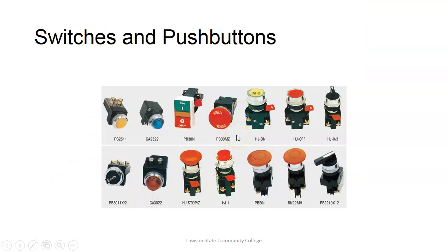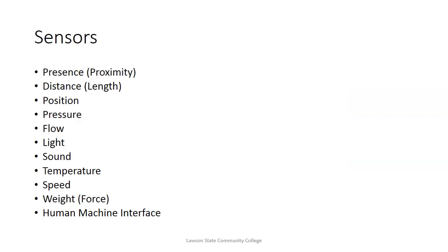So these are selector switches or push buttons. These don't have a polarity, so there's no such thing as sinking or sourcing push buttons. So this doesn't make any difference. When you get into your solid state sensors, this is going to actually come into play. So, sensors.